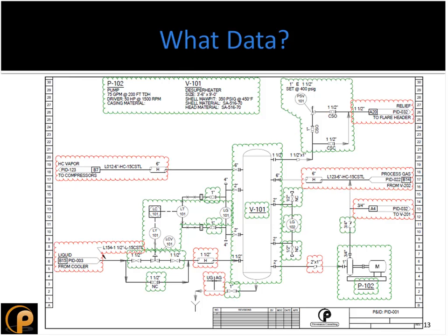And finally, you have your piping information and your line specification. So you can tell the size of the pipe, the process, the rating, the material. You may be able to tell if it's insulated or not, and any changes in that pipe, such as above ground, underground breaks, or metallurgy changes. And then just by looking at the flags going into and out of the drawing, you can tell where the process is going to or coming from. So there's all this data on your drawings.